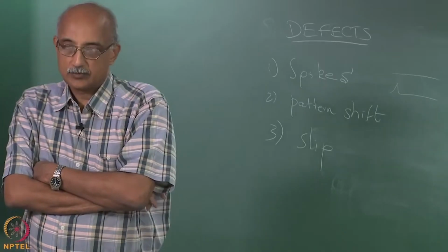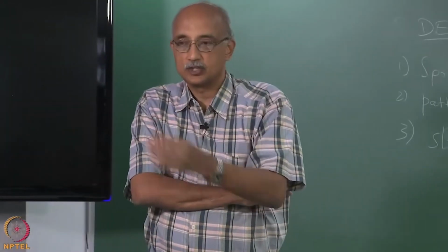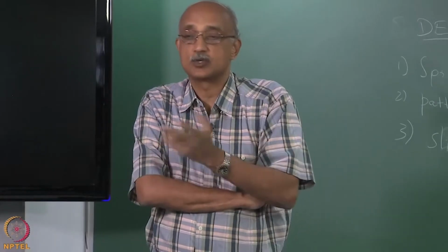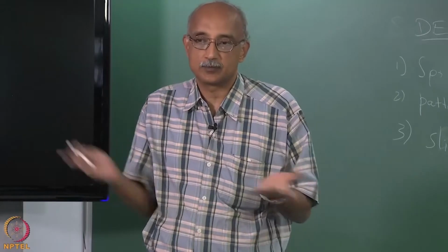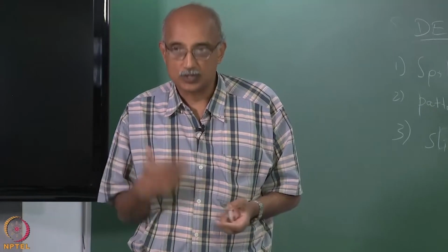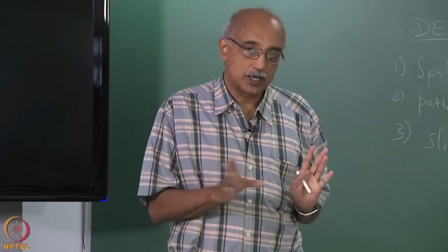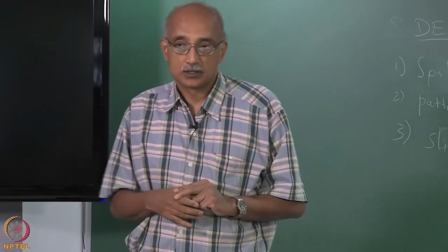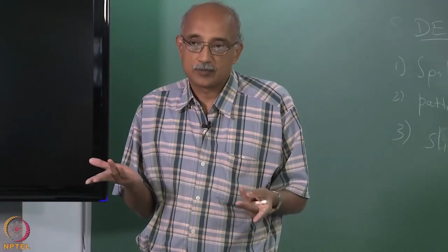So, the shelf life of the material, the properties you have discussed, yes. Shelf life also changes for the different types of metals. True, but once you make the CVD film on a surface, it will typically get used in the next step of the process within a few hours usually, or at the most within a few days. I mean, you are not going to make a CVD film and put it on a shelf for months or years at a time. Typically, these are used for high production processes. Now, there are certain products like CVD coatings, which have to have a lifetime of the order of years. So, for those films, shelf life should not be an issue.